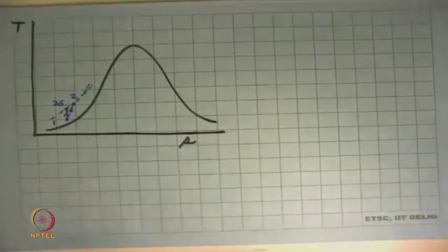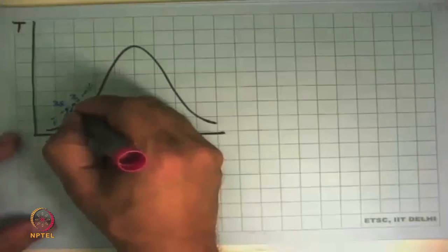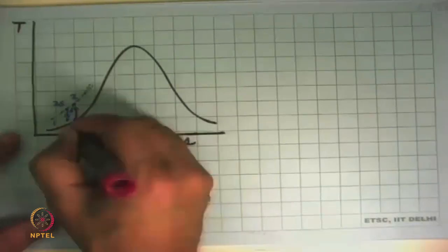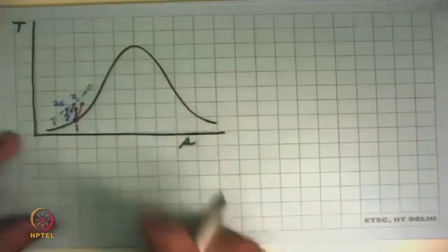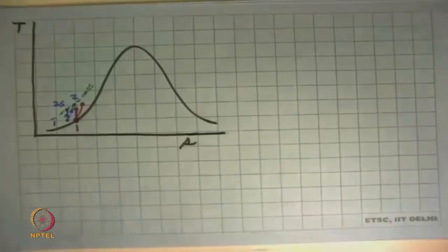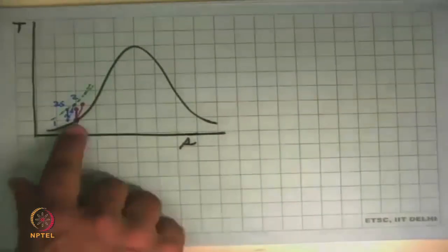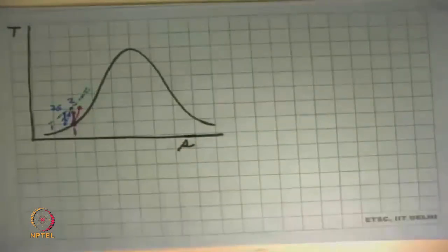If you are saying that we take saturated liquid and then we compress it, and that's what happens in a power plant, where we have condensed the water into a saturated liquid and then we start pumping it. So we can say that the initial state was here, and then we started pumping it and it went there. So it started as a saturated liquid at state 1, went here, and in the ideal case it went slightly over there. Okay, so that's the pumping of a saturated liquid. In the practical world, this is a very tricky operation. So pumping saturated liquid, where do we encounter it?